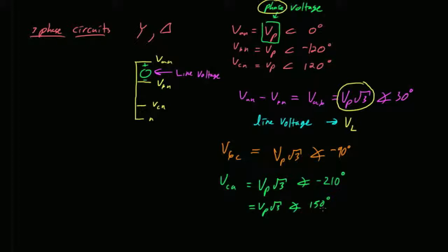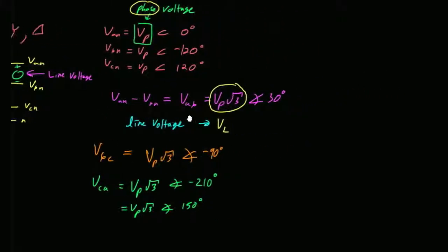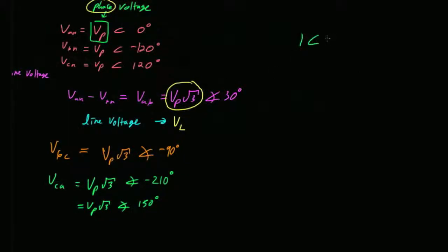Well, in theory, if you were to take this phasor minus this phasor and work the complex algebra, you'd get minus 90 degrees. Right? If you were to take one angle negative 120 minus one angle positive 120, and do that subtraction, which, I mean, this is VBN and VCN, so their difference becomes VBC. So how would you take that difference?